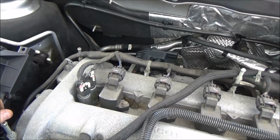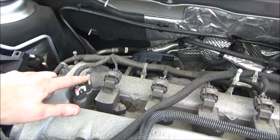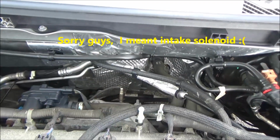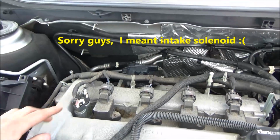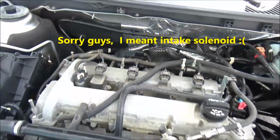Again, the fault we're dealing with is the exhaust cam circuit fault for this solenoid here. This is going to be our exhaust solenoid here on the exhaust manifold side of this. This other one's going to be the intake solenoid. As we can see, that's on the intake side of this.